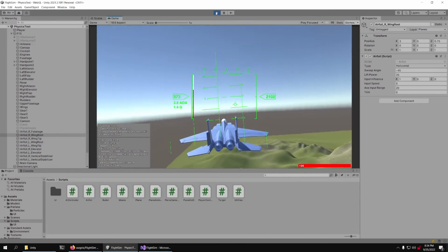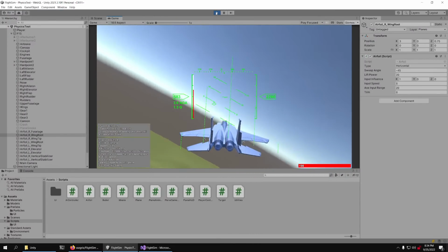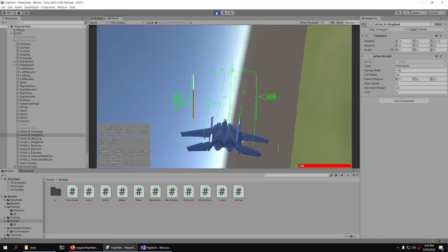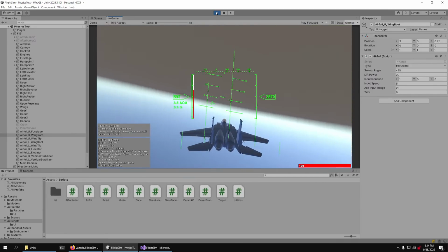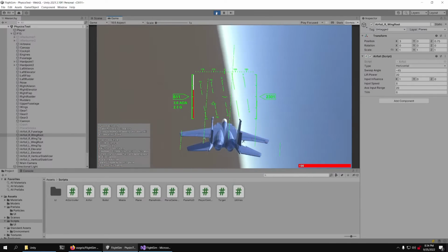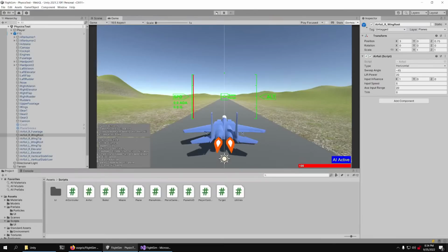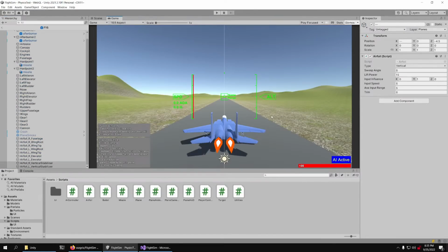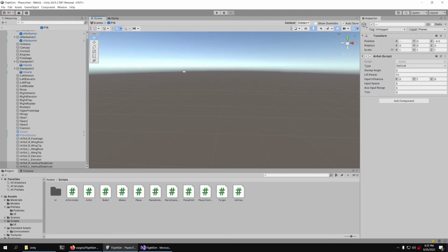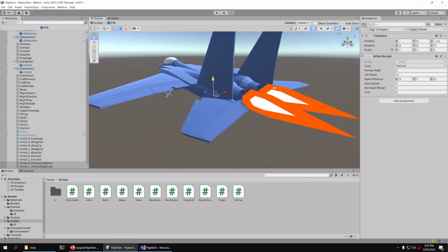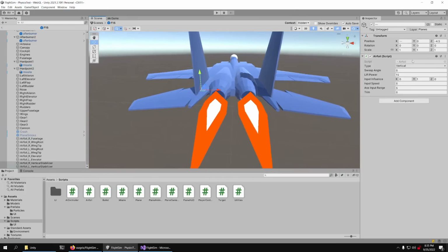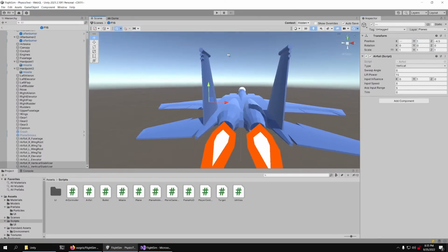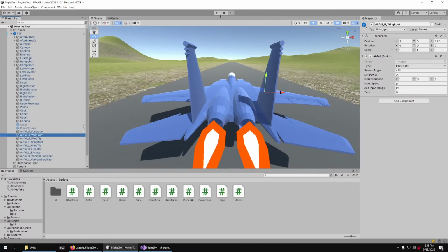Okay, so just by changing the sweep angle of the wings, or by inverting them all, now I get the expected behavior, which is right rudder causes a right roll. And we can go back and change the vertical stabilizer to be above the center of mass again, and see if this actually has the correct effect, even whenever they're producing torque in the opposite direction from their vertical offset.